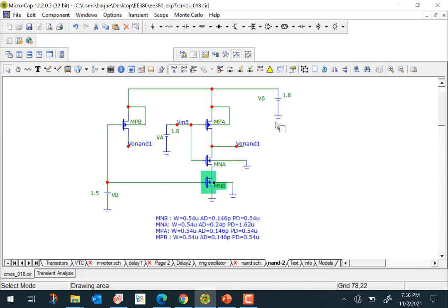and you can simulate it. And so again, what I would suggest is that you simulate the voltage transfer characteristics, the static characteristics, first, and this you can do in different ways. So for example, you could keep input A high, which is 1.8. And then you could vary the value of this particular input here. You can go from 0 to 1.8 here, and then see how the output varies. And then from there, you'll get a particular VTC, and you can measure what the noise margins are.